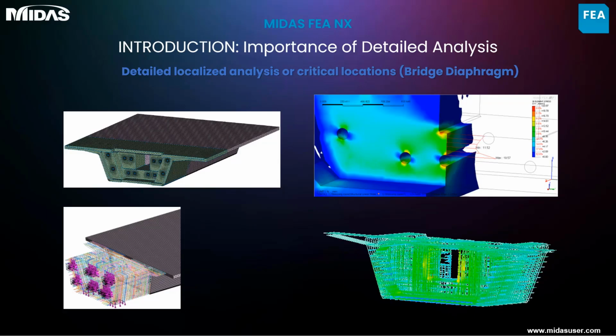Before diving into our model, I forgot something. I would like to briefly discuss two project applications of MIDAS FENX where our clients found the tool particularly useful. One involved the construction of a metro bridge with several simply supported spans. The design had been approved and the contractor was proceeding with rapid construction. However, after 6 spans were completed, cracks began to appear in the diaphragm of the first span. In response, a 3D model with reinforcements was quickly developed in MIDAS FENX, and based on the analysis, it was determined that these were merely surface cracks. Construction resumed only after this was confirmed.